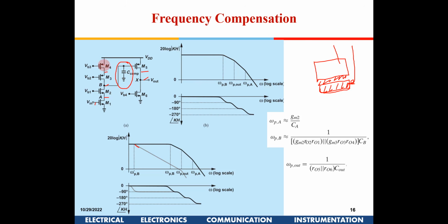Okay, sir. So this is not an intrinsic capacitance, mind you. This is an extra capacitance which we are going to put here to get this response. Now, if I have to find this RC value, what is the resistance as seen into this node? It will be gm R0 R2 in parallel, like we saw, right? So this capacitance along with the resistance seen at this particular node is the dominant pole now.